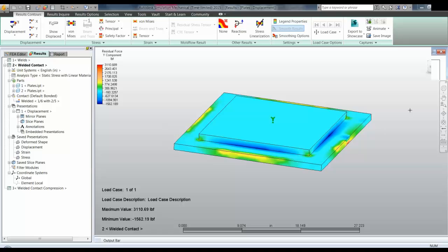But as far as reaction forces, they're going to be quite similar between parts. So if my goal is to get the reaction forces, I may not necessarily have to do that convergence study. But if I'm looking for stresses, then I do. Royce says that we have just seconds to go, so I'm going to stop talking and let him continue.